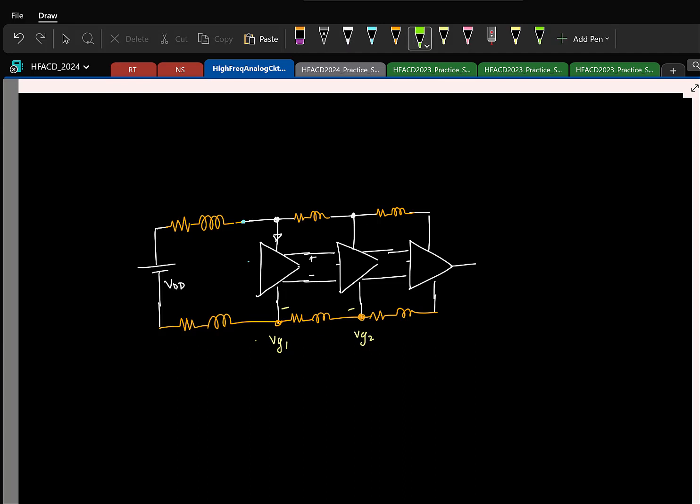So now let us say the ground changes for the first block, let us say there is a sudden jump in the ground. Remember, ground is the reference to this circuit. If the reference to this circuit increases slightly, what can you say about the voltages here? They will also change by the same amount, right? I mean, the ground is 0, that's a reference. If the 0 is not 0, all the potentials in your circuit will change. So both these lines will change by the same amount. If you take the difference, it's okay. Okay. So that is the idea, and this is typically called differential signaling.